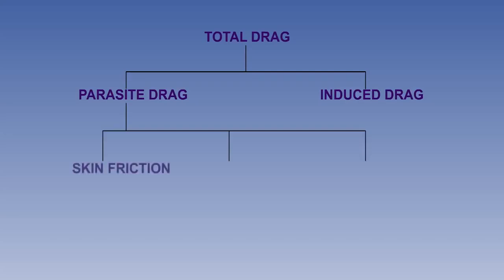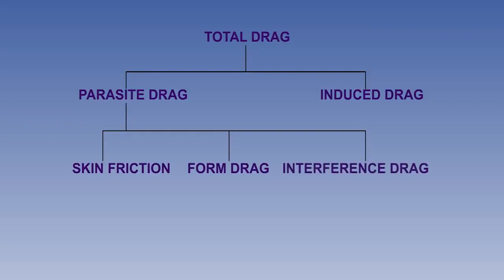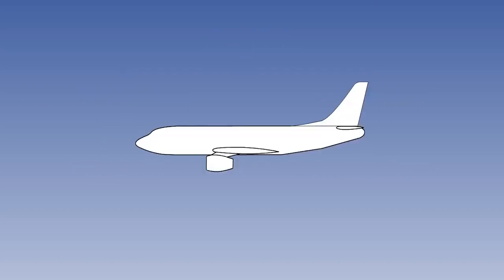If an aircraft were flying but producing no lift or downforce, the only drag present would be parasite drag, which, as already seen in the drag family tree, is comprised of skin friction, form, and interference drag. An aircraft's skin, regardless of material, will to some degree have imperfections or roughness in its surface, due to paint, rivets, and other protrusions, contamination, etc.